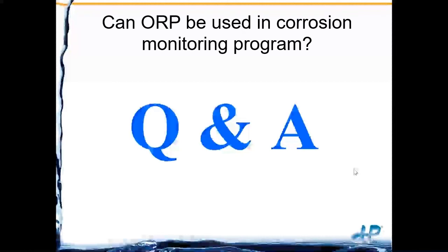Can ORP be used in a corrosion monitoring program? This is actually something that, yes, it can be done. From my standpoint, I can't tell you what millivolt value you're going to have to maintain it at, so someone there has probably done some investigation. I can tell you that EPRI has done some investigation, but as far as I've seen, it's not been finished. They've done it on copper pipes.